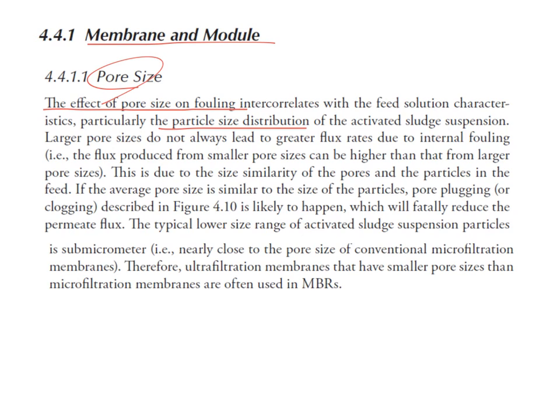We already mentioned fouling mechanisms such as pore blocking or pore narrowing and cake formation, and we know that pore blocking is one of the most serious fouling phenomena because it can readily cause irreversible membrane fouling.